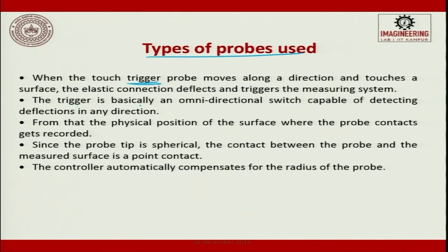Trigger is basically an omnidirectional switch capable of detecting deflections in any direction. Omni, multiple, any direction. From that, the physical position of the surface where the probe contact occurs gets recorded. So, wherever it touches, the trigger is done and immediately XYZ data is recorded.